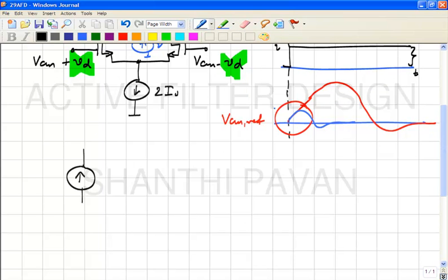So I have put in a step current I, and the change in the voltage... there is a capacitor here, correct, and what is the rest of the story? As C tends to 0, the slope goes to infinity, so there must be an inductor.